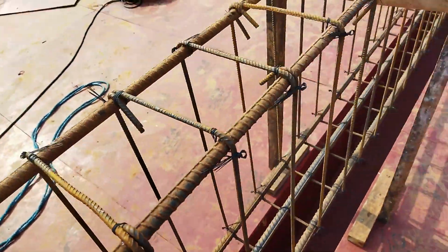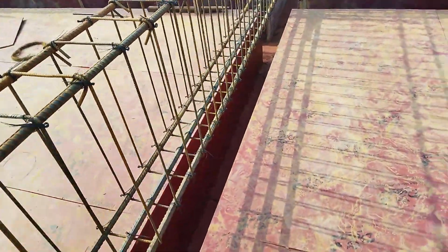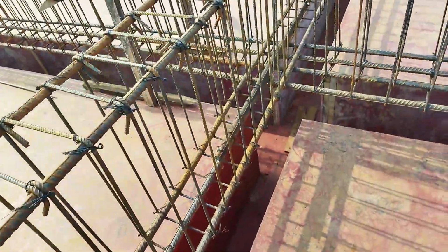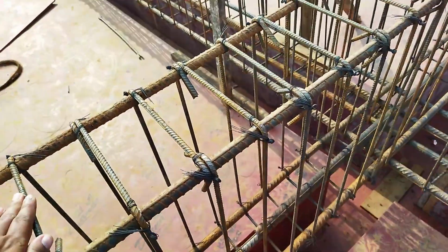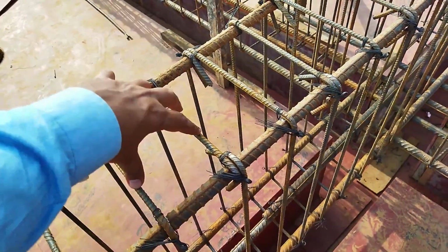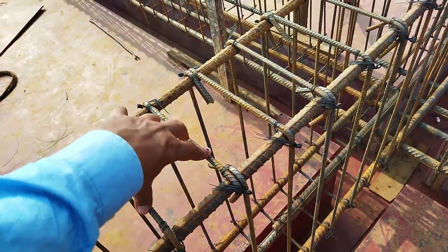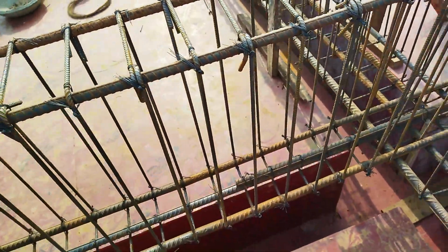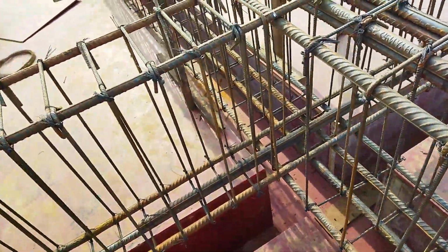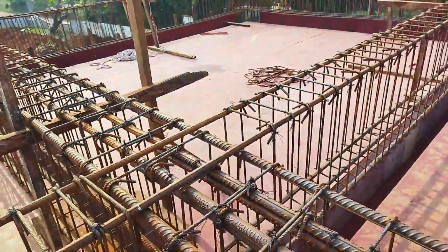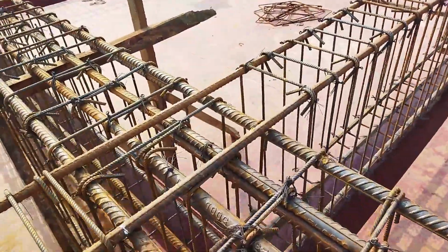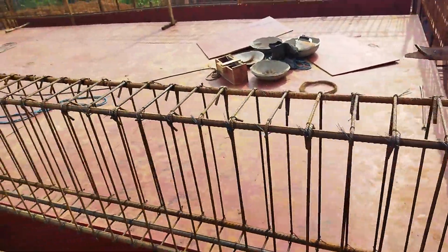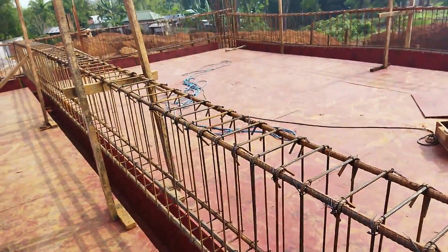These are some things which you can observe at the site: the diameter of these particular bars, the diameter of the stirrups, and the center to center spacing between 2 stirrups. Here it is 100, 125, whatever; you can check the spacings. And if there are extra bars, they have not fitted them yet, they will provide them shortly. So the extra bars also you can check. Now we'll move on to the drawing and see some of the aspects of the drawing part as well.